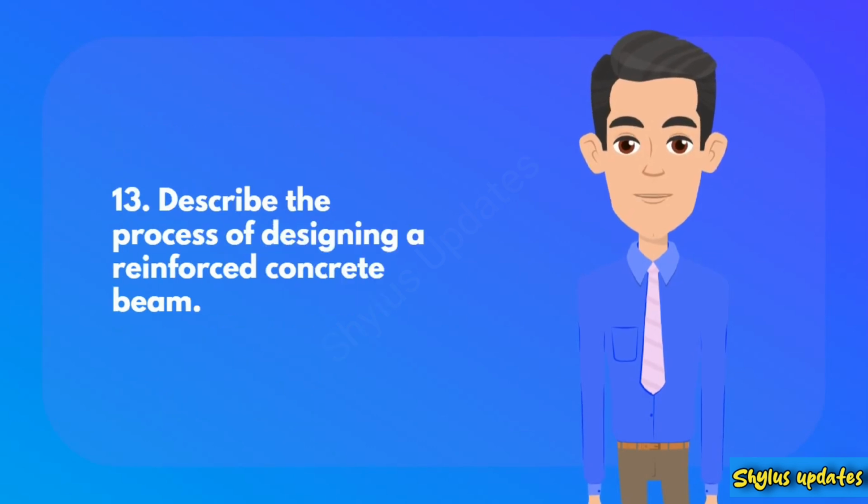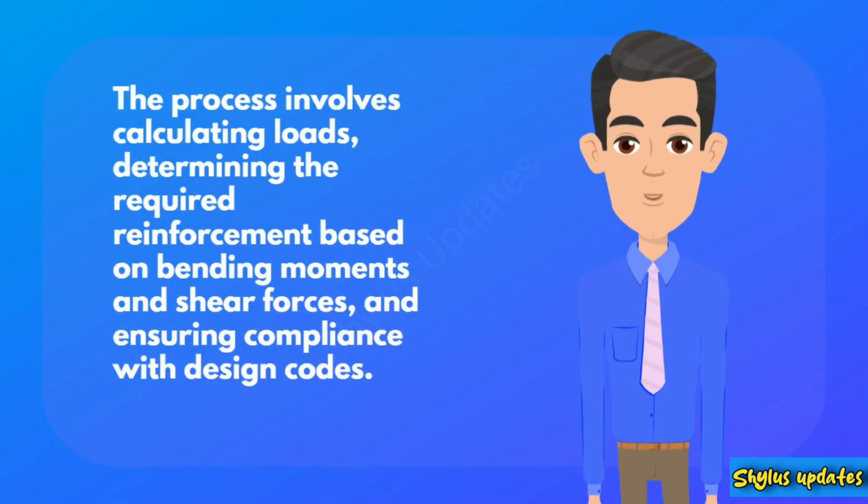13. Describe the process of designing a reinforced concrete beam. The process involves calculating loads, determining the required reinforcement based on bending moments and shear forces, and ensuring compliance with design codes.